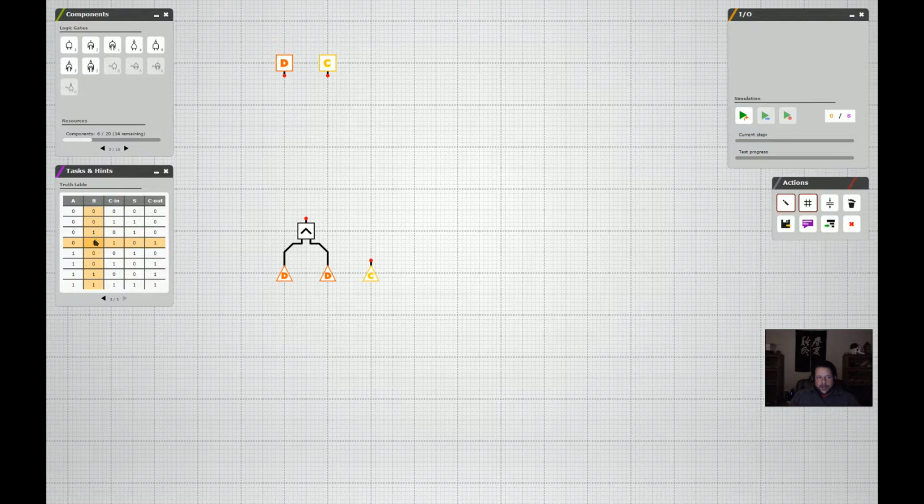So the next four, the result of A and B will be a 1. So a 1 and a 0, output is a 1. A 1 and a 1, the output is a 0. A 1 and a 0, the output is a 1. A 1 and a 1, the output is a 0. Okay, that sounds an awful lot like another XOR between the AB combo and the Cn.